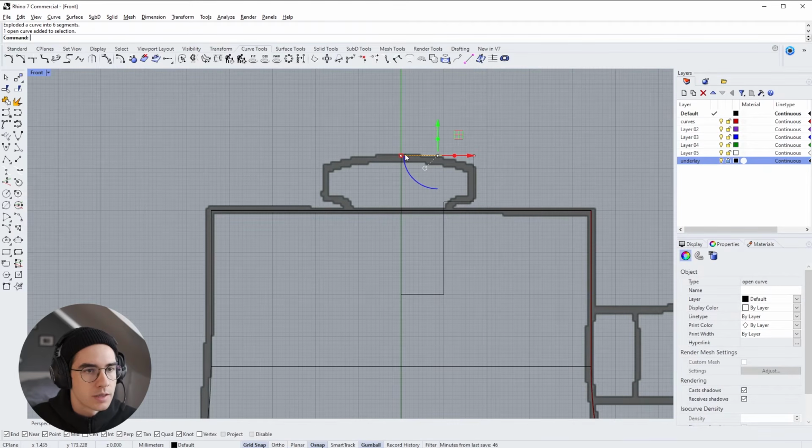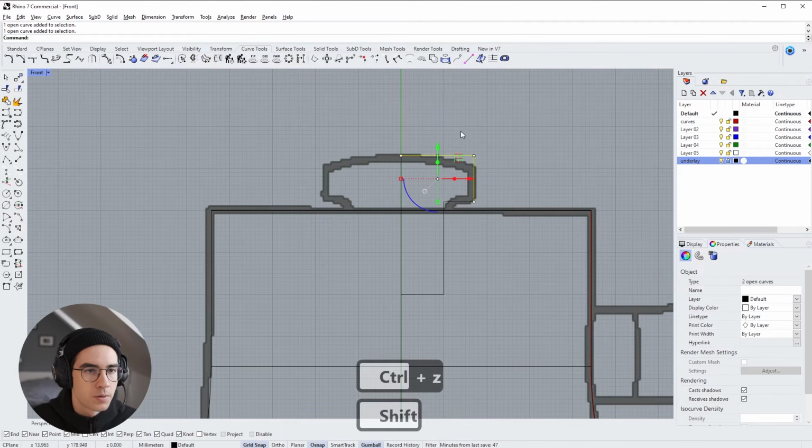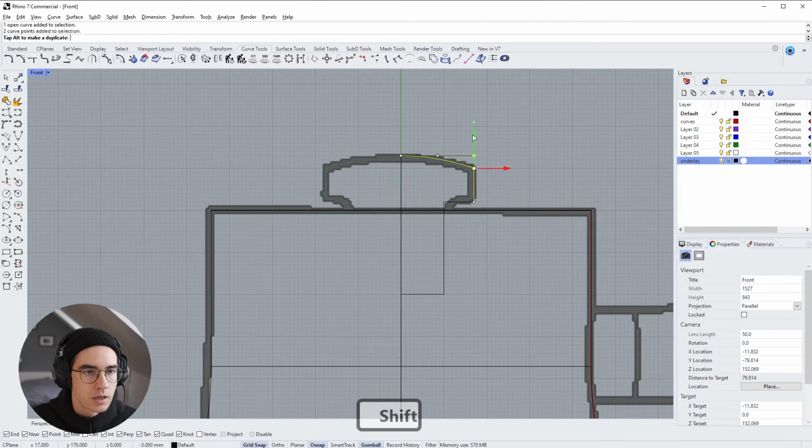In order to create this sloped shape on top, we need to bend it down a little bit. So what we can do is change degree, change it from a 1 degree line to a 2 degree line, which gives us 3 points to interact with. I'm selecting both lines, select the corner and drag down a little bit, and that creates the perfect sloped curve here.